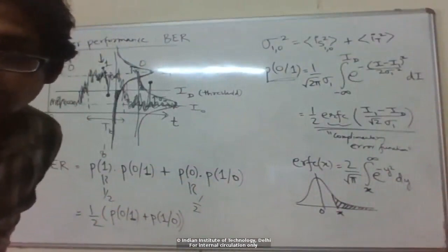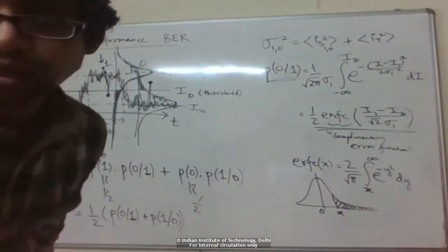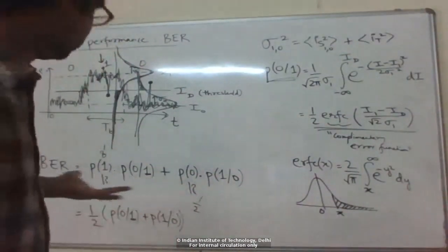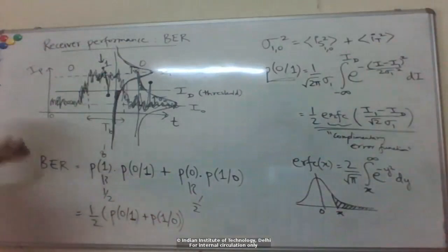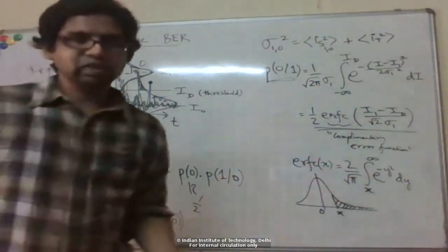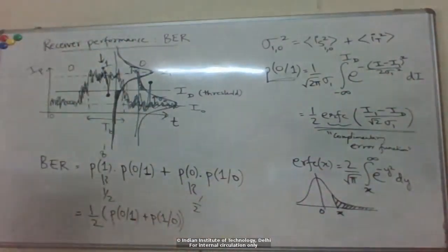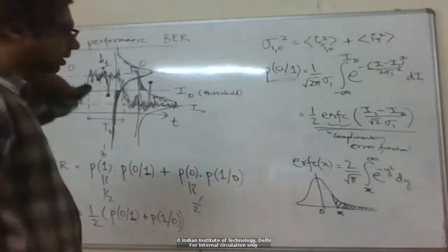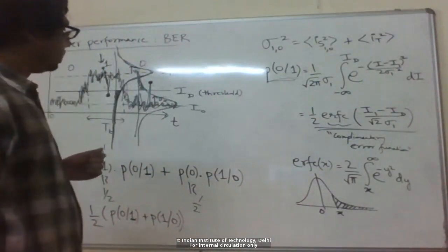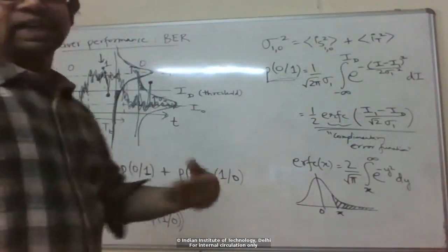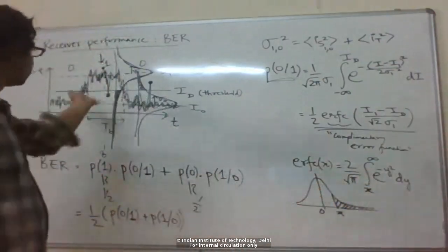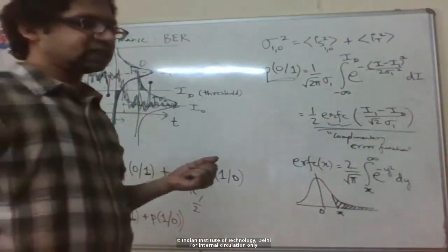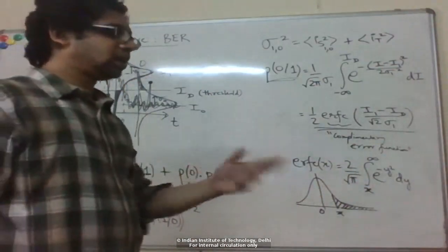There's a question, why is it called bit error rate? It's just the probability of making a false decision. More precisely, it should be called the probability of error rather than bit error. It's not a rate in time, like the bit rate. But you can think of it as a rate in the number of samples.